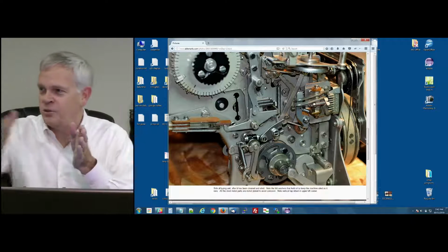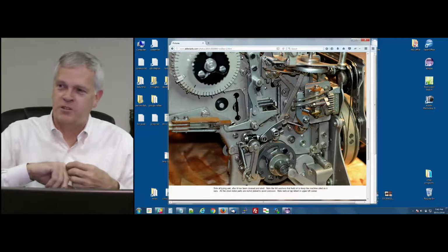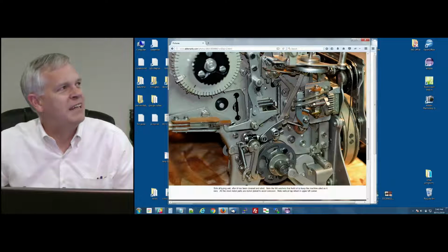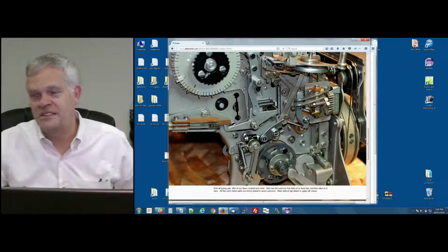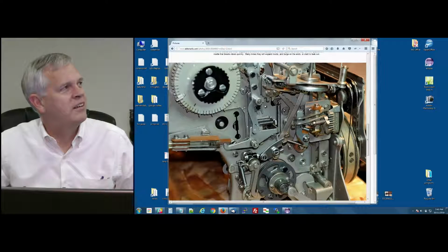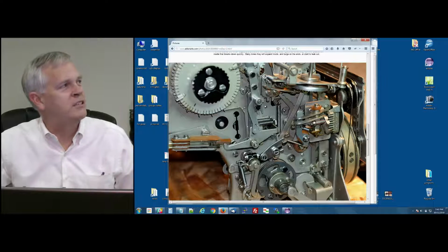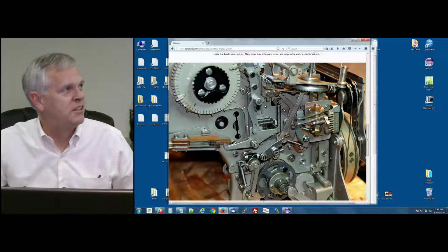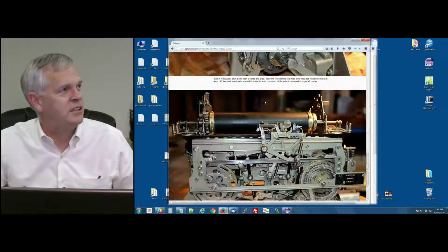This here is a device which is a vertical tab. Everybody knows horizontal tab, but on these machines you can also have vertical tabs. You say go up 5 lines, go up 10 lines, go to the next page. And you set those by taking these little tabs and rotating them up or down, depending on whether you want it to stop. And this happens to be the page tab. These are lines. It was 66 or 70 or something like that? Yeah, and you can't quite read the numbers, but it says 11 over here, and that's 5.5 inches, and this is 11. So if you took that out, it would do the whole page. Or if you have this one, now it's going to do half pages on the page feed.